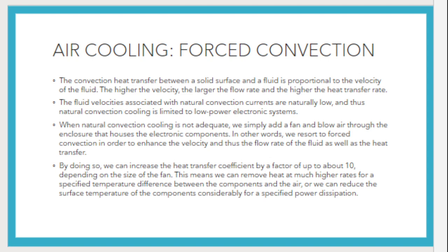Air cooling, forced convection. The convection heat transfer between a solid surface and a fluid is proportional to the velocity of the fluid. The higher the velocity, the larger the flow rate and the higher the heat transfer rate.